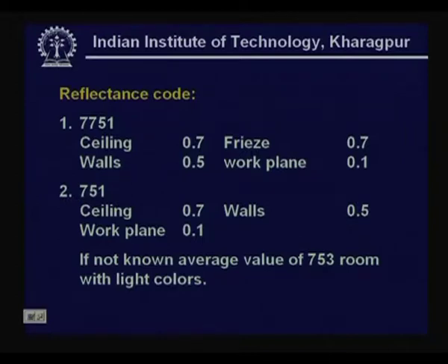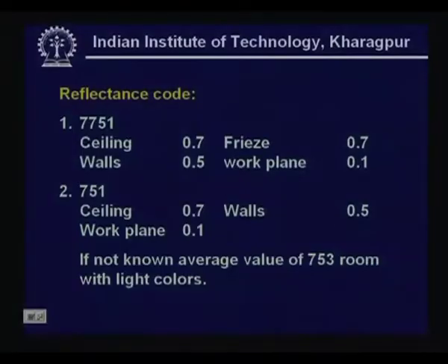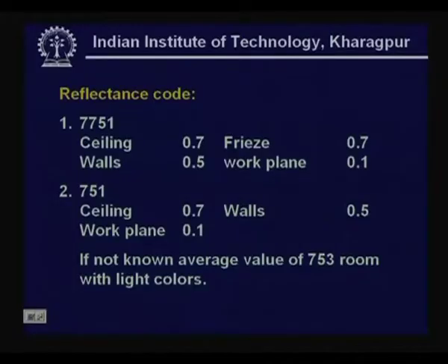We do find that oftentimes the roof is painted white and the walls, unless for a personal choice, are light creamish, light greenish. These are the types of colors that are employed. So, one may take 7.5, and possibly the work plane may not be as good as we expect it to be towards the ideal. So, a factor of 3 for reflectance, 0.3, can be taken.